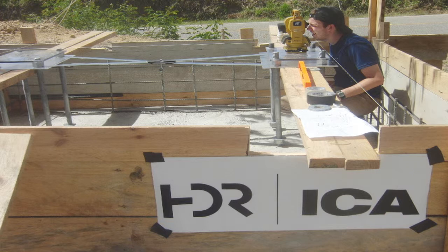Okay, the way we did that was we had aluminum plates made that represented the base plates. Threaded our anchor bolts through there, and then we've got these 2 straps coming across here, and that was machined in such a way that if we got this all assembled right, it would automatically cause those 2 groups of anchor bolt patterns to match up correctly, okay, relative to each other.